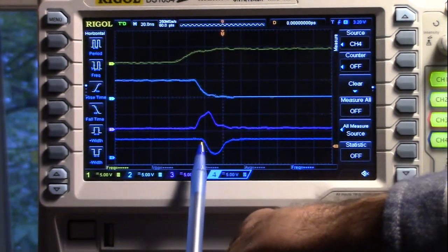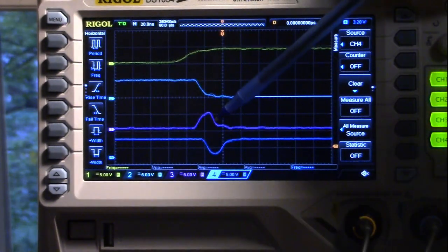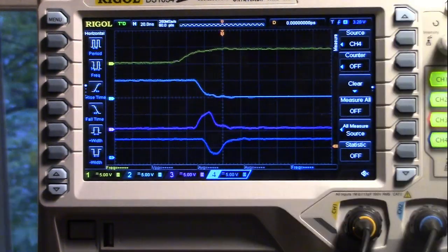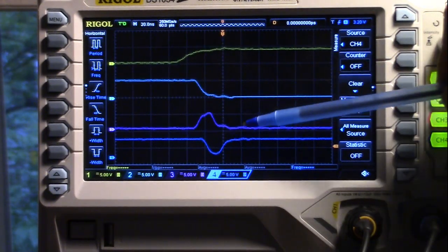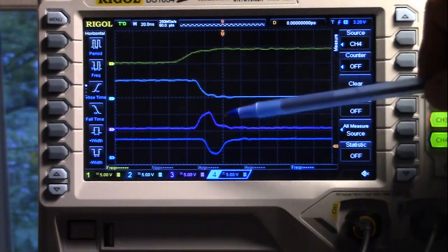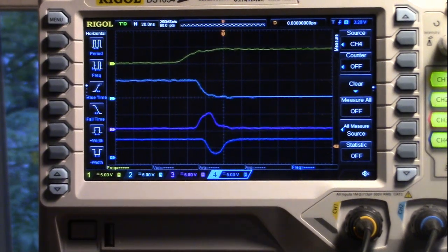We invert that count, the most significant bit, which is to say QB. We get about a 20 nanosecond low pulse going into clear, and since it's an asynchronous clear, that's enough to cause both outputs to go to 0. When QB goes to 0, clear goes back to 1. So we actually are counting 0, 0, 0, 1, 1, 0, but it happens for such a short time that